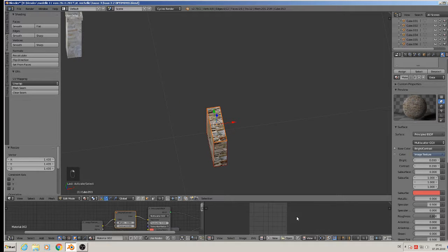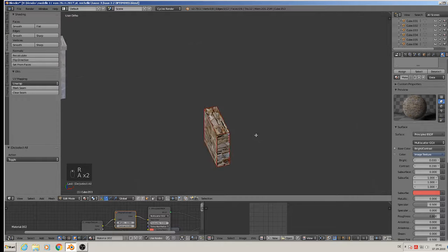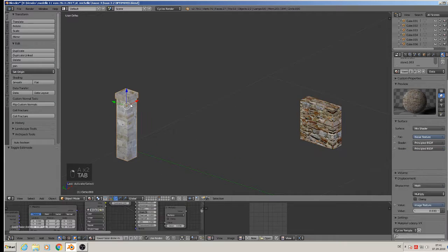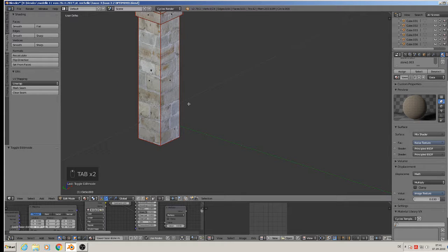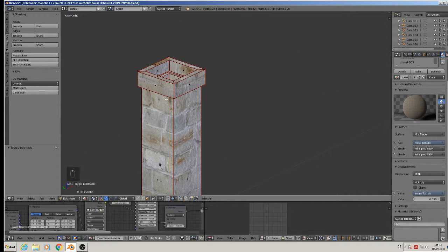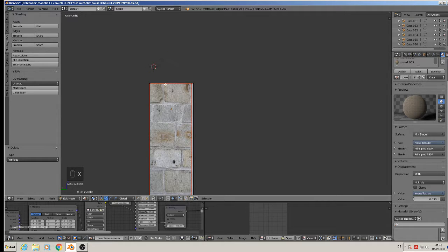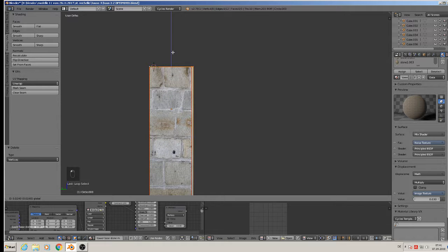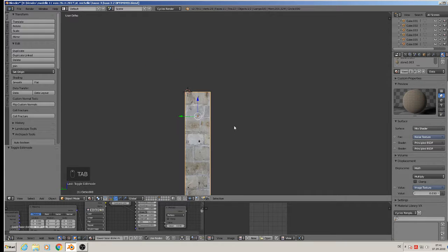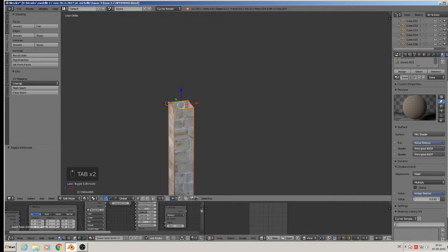Here you may turn that, rotate 90, and it looks a little bit better. Good. Here we only have the problem that it must be closed, so we simply can go here and take that one here, then Control plus takes the next stage. I make here my 3D cursor as reference, then X, delete vertices, and now I need only bring that up to my reference, and I have the same height. All is fine, and it has fewer vertices.